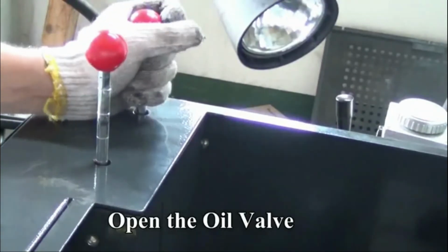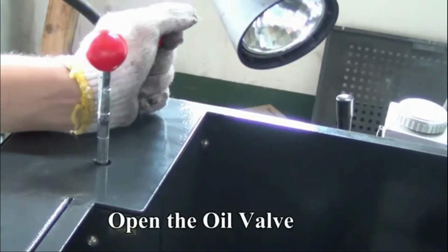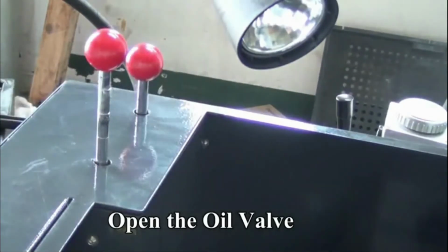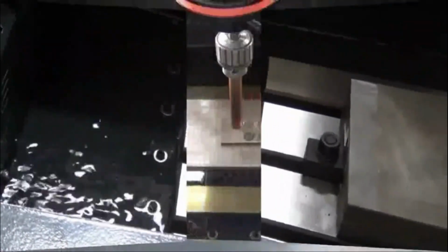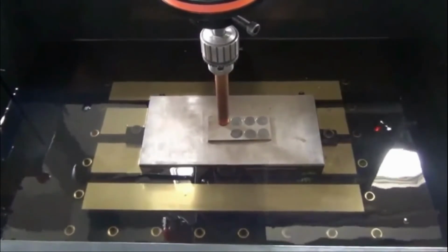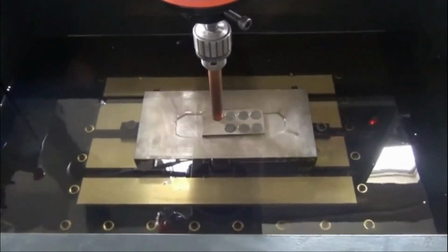Next, open the oil valve, because we want to submerge the workpiece and the electrode into the dielectric fluid. For that purpose, we open the oil valve. Whatever oil is present, either kerosene or EDM oil, acts as a dielectric between the electrode and the workpiece.